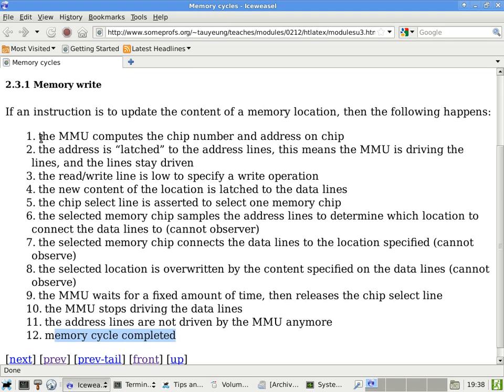Now the memory chip will wait for a certain amount of time to give me the content of location 88. But at the same time, the processor and the memory are now synchronized. So I will wait X amount of time for the memory chip to respond to the first location. So you would tell me what is on page 88. Then I will wait a little bit more time, and you will tell me what is on page 89, without having to go through all this trouble again.